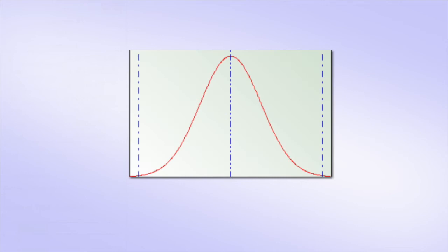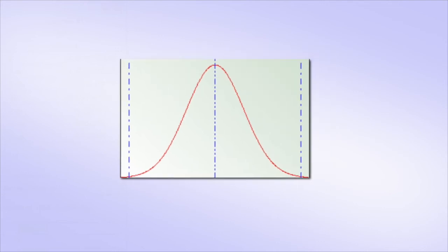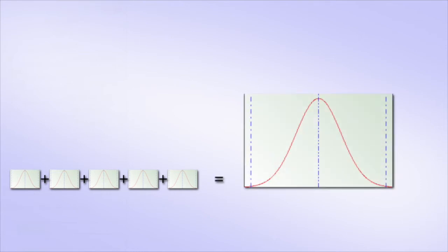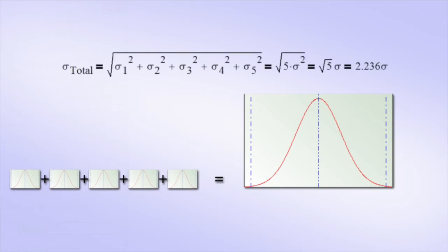The simplest textbook-like solution would be to assume normal distribution and independency in the tolerances, and so the standard deviation of the resulting dimension is the Pythagorean sum of the individual standard deviations. When all these are the same, the individual tolerances can be extended by the square root of the number of tolerances used. In our case, they all can be extended by about 2.2, making the production notably easier and cheaper.